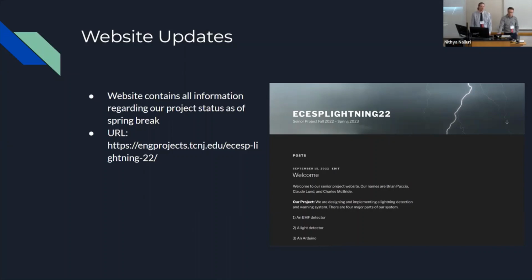So we have a working breadboard for our conditioning circuit. And essentially what that's doing is it's taking the input from the RF signal and turning it into a DC output based off the frequency. And we have a set level at the ADC that it's being sent into. So if it's above this value, it's a good signal. And if it's below it, it's not. So inside of there is an LCR bandpass filter centered at 300 kilohertz, and it has a really short bandwidth. So if it's really outside of that range, it's going to produce almost nothing. So that's just to make sure that we're really dealing with exactly the frequency we want.